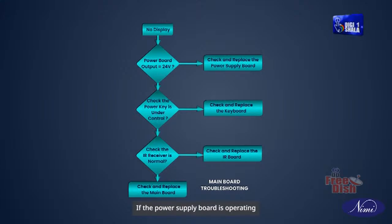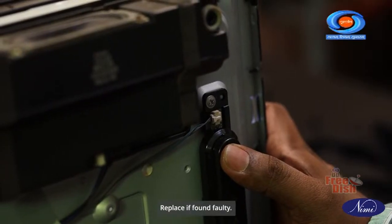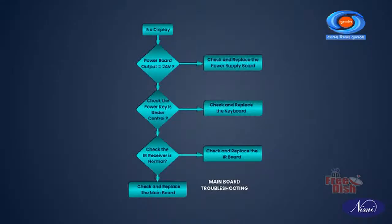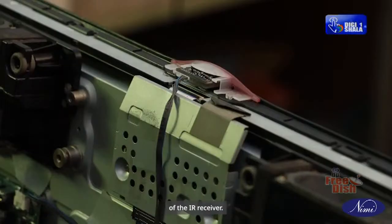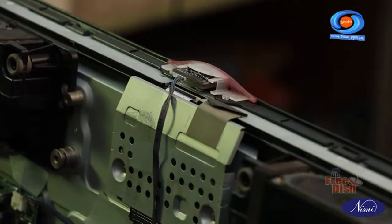If the power supply board is operating correctly, proceed to inspect the functionality of the power button on the front panel. Replace if found faulty. Next, assess the performance of the IR receiver. Replace if necessary to restore signal reception.